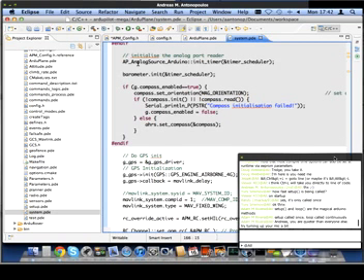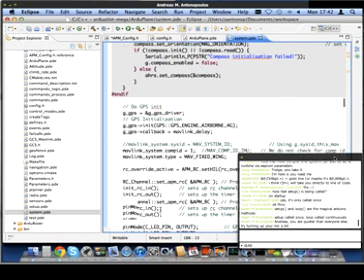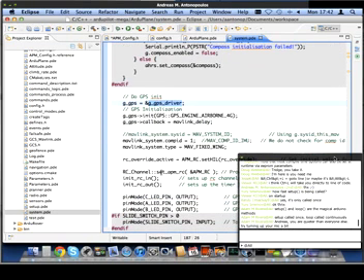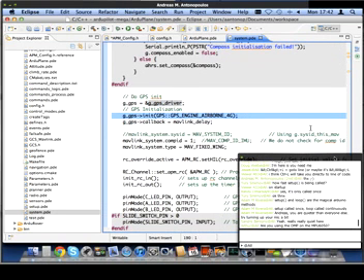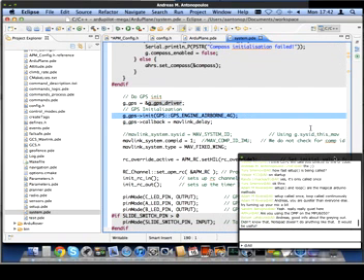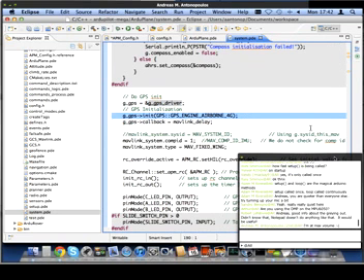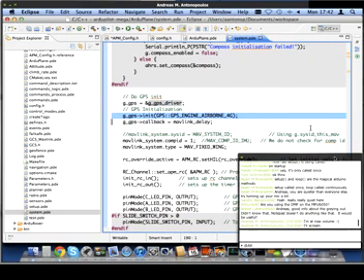Yep. Also inside this initialization, we initialize, as Andreas says, the compass, if you've got a compass, and the GPS we can see there, and quite an interesting one. If you have a look at that GPS init line, that's something we've changed quite recently. There we set a parameter to say how to configure the GPS. This is only for u-blox. If you have one of the new 3DR u-blox and you're using ArduPlane, then it will automatically configure the GPS for airborne 4G mode, up to 4G turns.